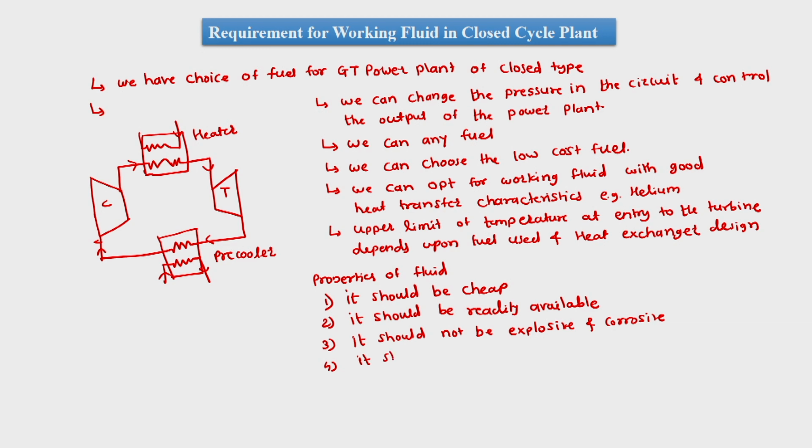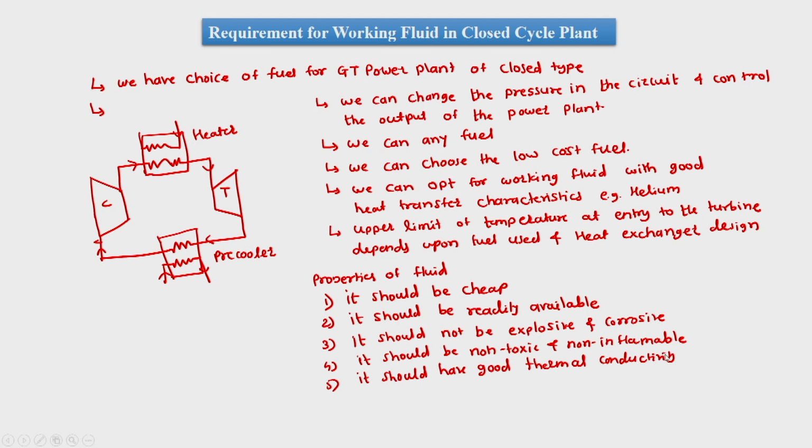It should be non-toxic and non-inflammable. Fifth, as said earlier, it should have good thermal conductivity for heat transfer, and it should have high Cp and gamma.